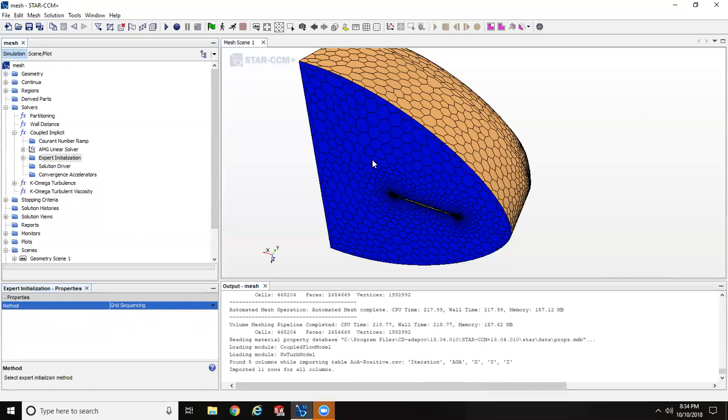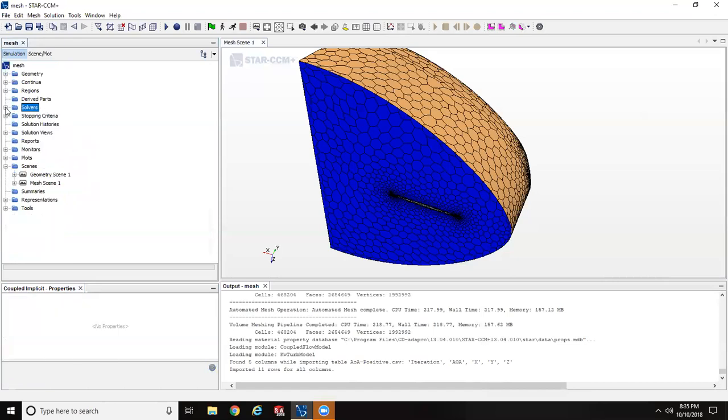You solve the solution on that really quickly. You interpolate that to a denser mesh, and so on and so forth, and it does it like 8 times until you interpolate that solution to the finer mesh, and then you initiate your solution in a normal fashion. So this really helps speed up the convergence of our solutions. So that's one thing that we want to do there.